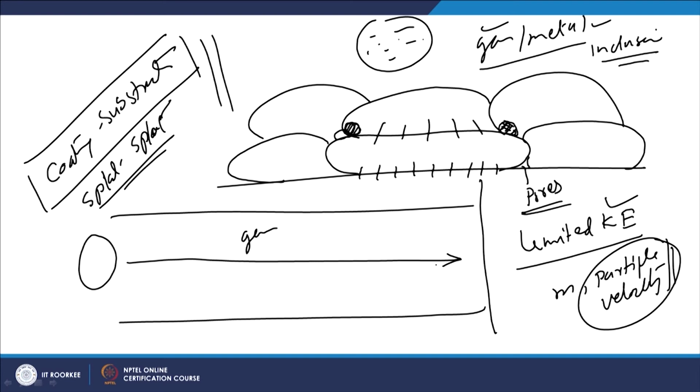If the nozzle to the substrate distance is very less, then these particles will not be able to attain much higher velocity, and that will be leading to a number of defects in the form of pores and limited bond strength. But if the distance is too much, then the particle velocity may also get reduced, and the stay of the powder particles in the molten or semi molten state at a higher temperature will be longer, and that will be leading to the formation of inclusions as well as an increased tendency of thermal degradation of the constituents in the powder particles.